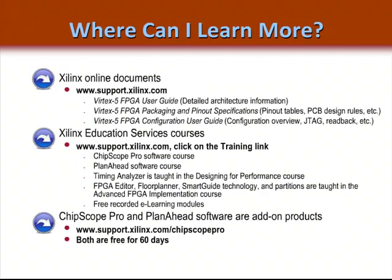Well, there are lots of places to learn more about FPGAs, and they all start at support.xilinx.com. To start with, you may want to review the Virtex-5 packaging and pinout specifications. This discusses design rules for PCB layout, provides pinout information, and other topics. The Virtex-5 configuration user guide provides more information on the JTAG logic resources and provides more information on readback.